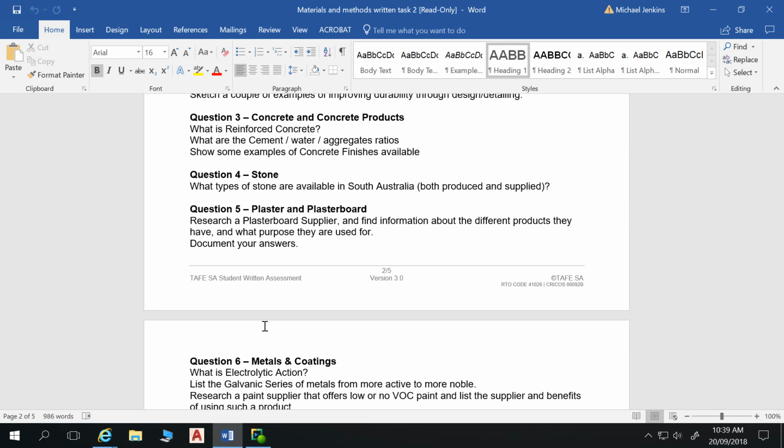Have you ever seen off-form concrete that looks like it's got timber look on the outside to it? There's a whole bunch of that stuff that was done at Adelaide. It's done all over the place. So I don't know if there's anything around the TAFE here. In one of my other classes, I've got a guy who's been a concreter and formwork maker for a very long time. He said at that Adelaide Oval development, that was the highest slump concrete he's ever seen, for getting into those timber look forms as well, because it's got to mould to all the fine details in that.